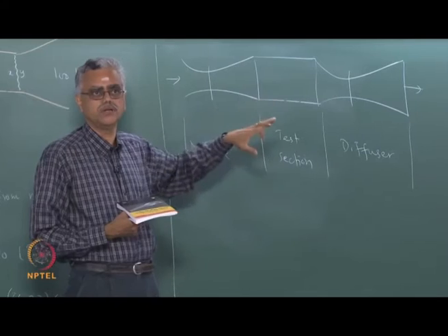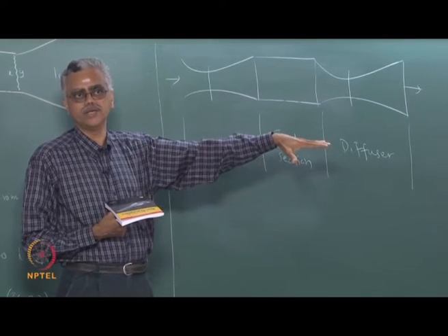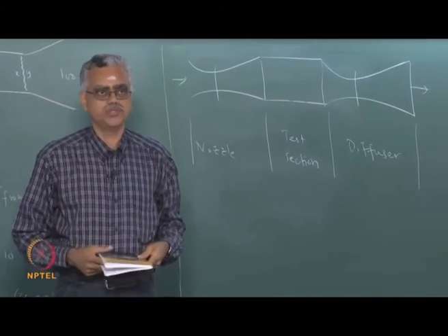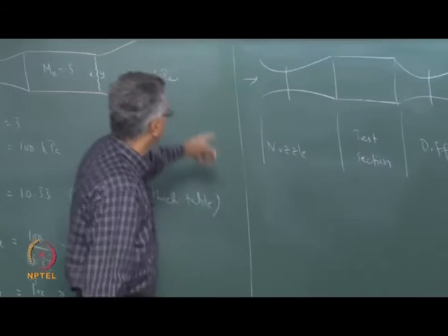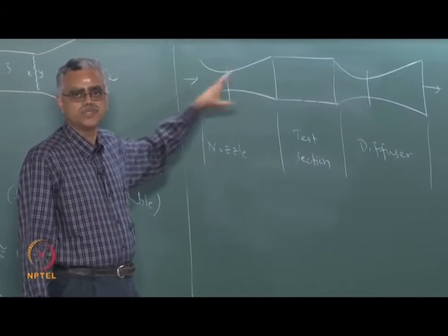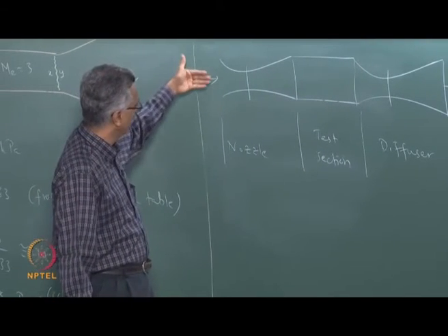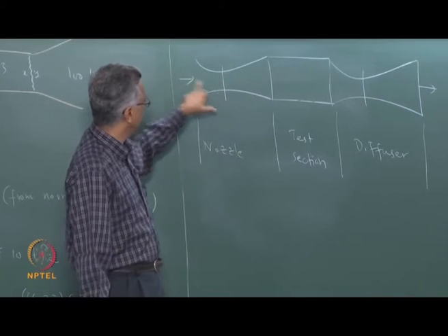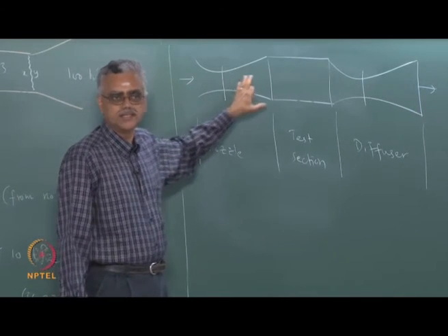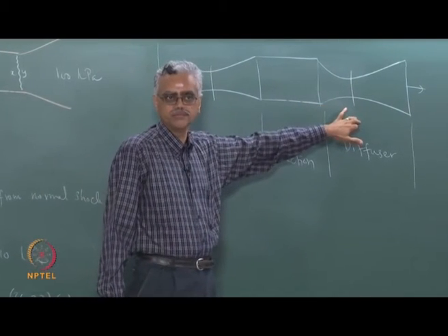In this case we are not lowering the ambient pressure. Yesterday when we talked about this, we were looking at keeping the inlet stagnation pressure constant and then lowering the ambient pressure. Now we are actually running the compressor. So, we are actually increasing the stagnation pressure, keeping the ambient pressure the same, right. So, I increase the stagnation pressure a little bit more. I now set up a situation where the flow accelerates, M becomes equal to 1 here, right, and then again subsonic flow throughout, perhaps M becoming equal to 1 here maybe.